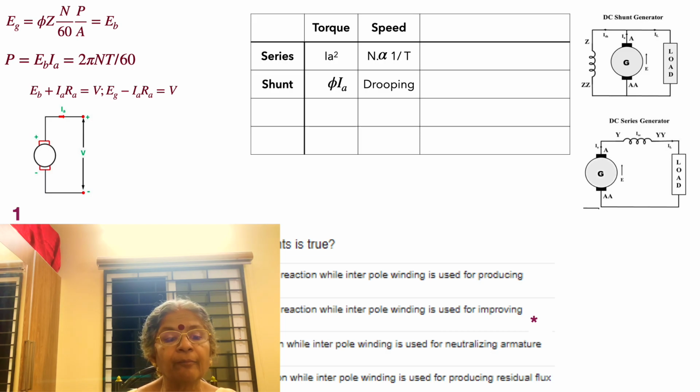When you are considering a motor, it's given by phi per pole, because each of these poles is responsible for creating the voltage. Z is the number of conductors, not just turns. In each of these conductors, an EMF appears as per Faraday's law of electromagnetic induction. N, every rotation counts. And P, every pole is responsible for creating a voltage. That's the meaning of this formula.